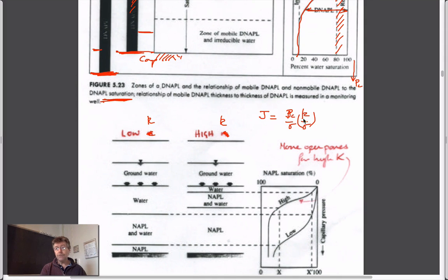So we know from playing around with this that capillary pressure, entry pressure, is proportional to N over the square root of K. Just from looking at this. This is a number for the bubbling pressure. It's 0.3. And so at bubbling pressure, then this relationship has to hold.